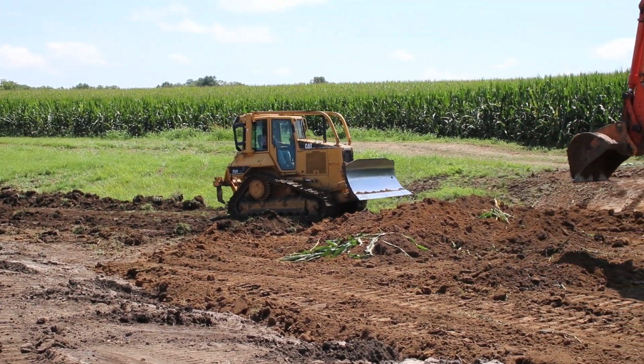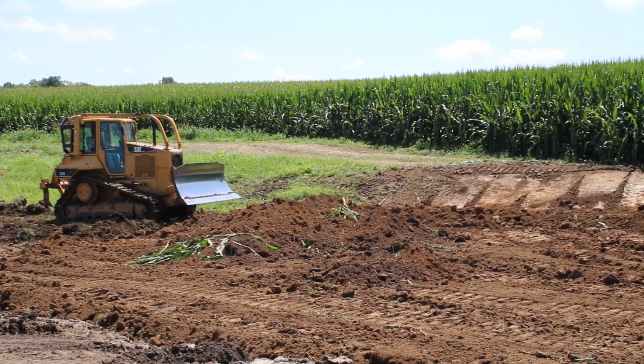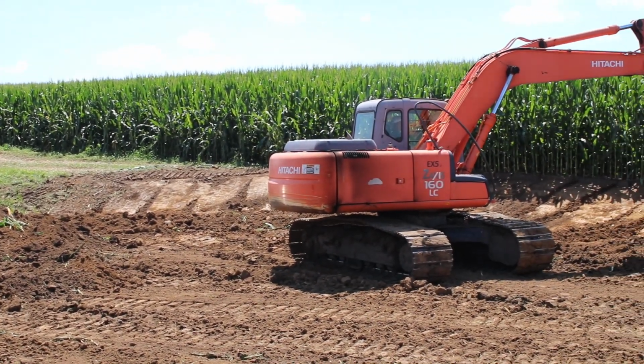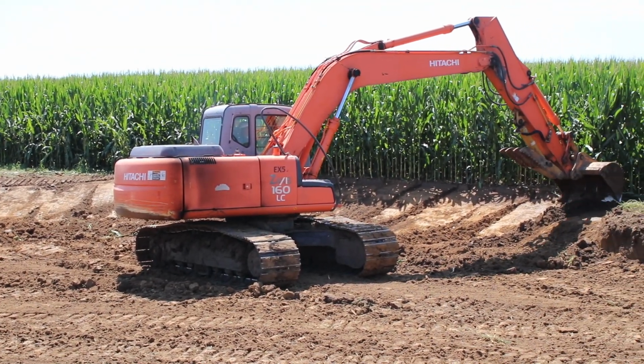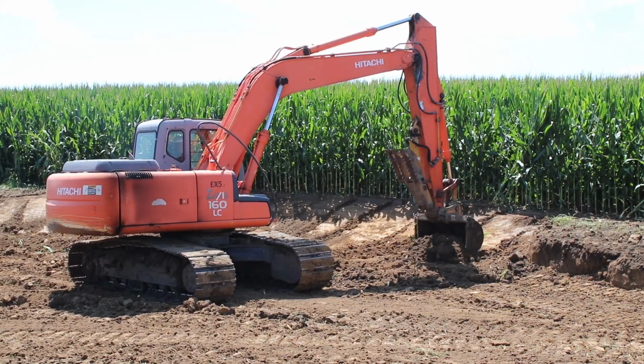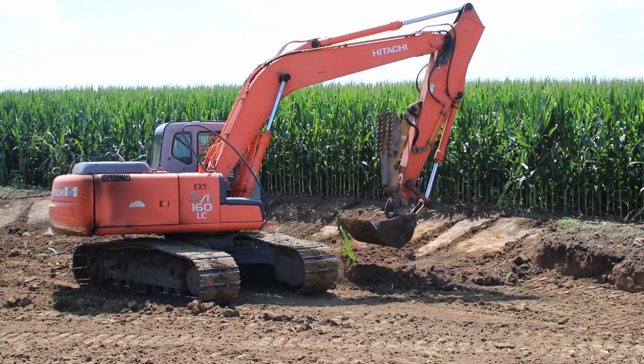Here they are constructing that low point to the south of the structure in undisturbed soil. If and when high flows happen, there may be some minor erosion in that low point, but it will be much easier and less expensive to repair than replacing the tied concrete block mats.